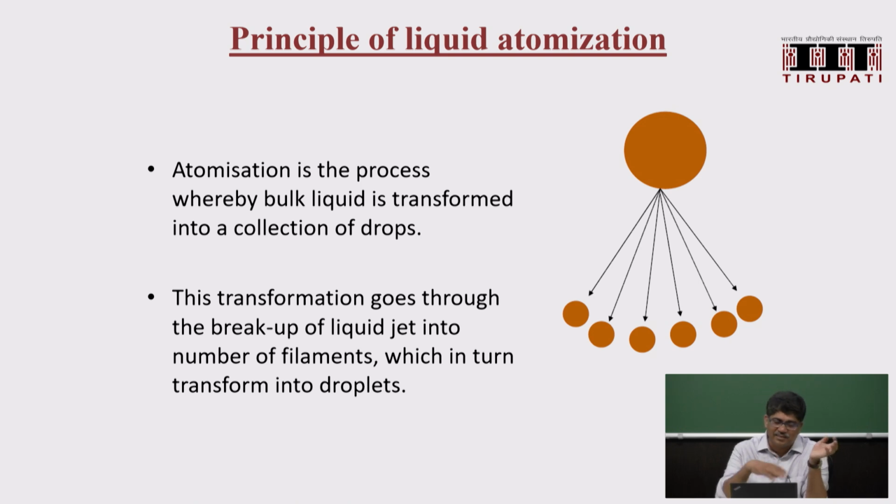So this transformation is usually done by first taking the liquid and making it into a thin liquid sheet, or into a jet. That sheet or jet first breaks into big drops, as we can see later in the images. If the drops are spherical, we call it a drop. If it is non-spherical but still somehow looks like a drop, we call it a non-spherical drop. If it doesn't even look like a drop, like big threads, we call it ligaments. If it is just a long stretched one, you don't call it a drop.